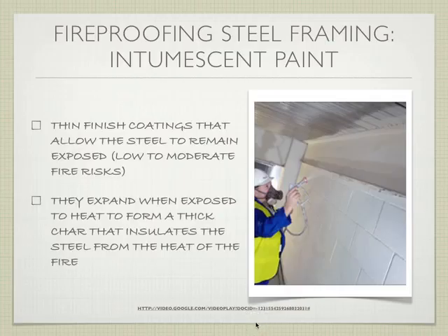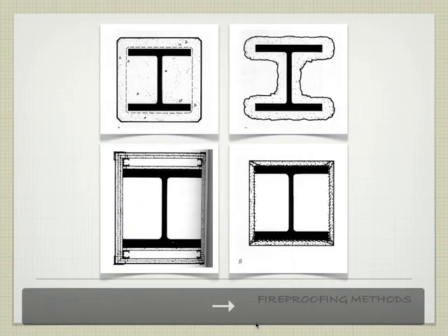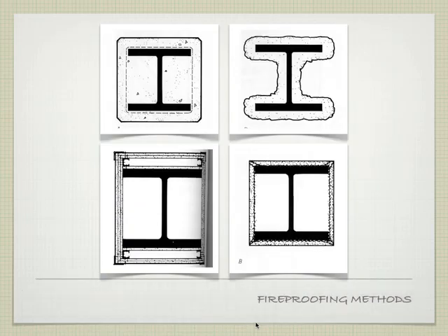Okay, so we're going to go back. I will see if I can load it over the break. Maybe I can preload it in one of the other rooms and bring it in, or load it up on this computer so you can see it. It's a good example because it shows two pieces of plywood. One is just regular plywood. The other has been covered in intumescent paint, and a time lapse shows how quickly a gas jet will go through the plywood and not through the intumescent paint. It's a really good example. So intumescent paint is really great for fireproofing buildings.